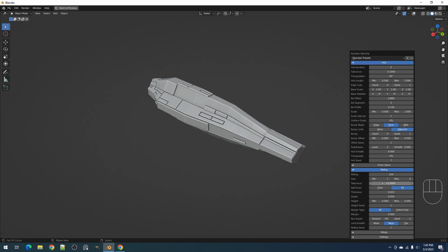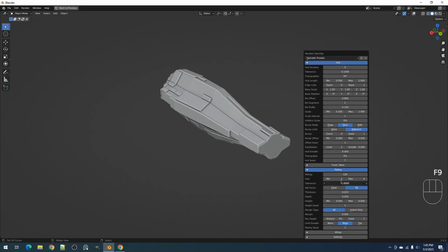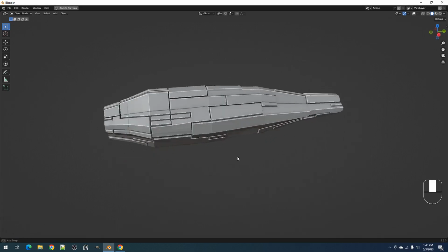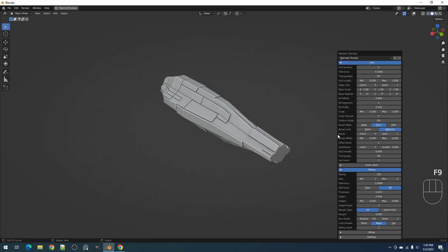The tolerance property is used to find faces for the plating details. The lower the value gets, the more it will try to get faces that have the same normal as the faces used in the plate inset. If you raise the tolerance, this will enable the plate inset to expand more by getting faces that differ from the average normals used by the plate so far. Think of this as selecting faces that have the same normals or plane.